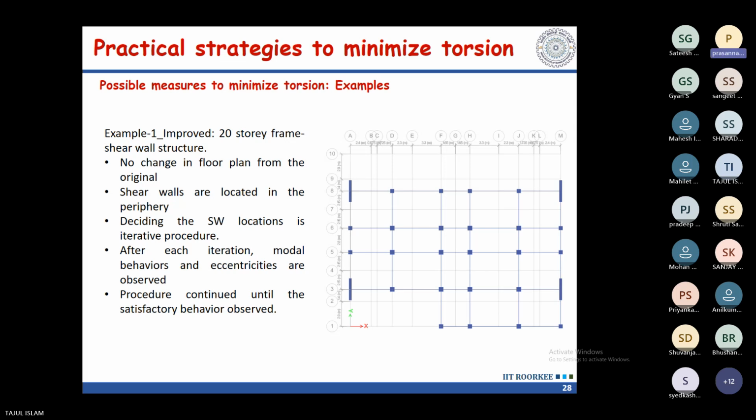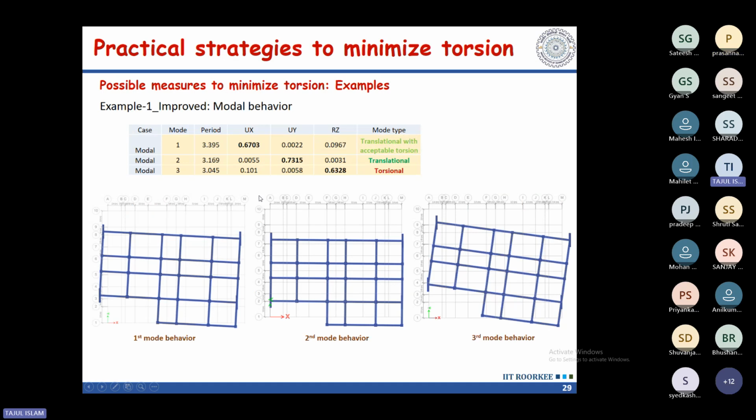But why are you giving a 60% basis for the torsional mode? Yes, I know that 60% is actually a reliable limit. The code says that the combination of modal participation from the first 3 modes should be 60% at least. Correct. But based on our experience, if it is less than 60% in the first mode, you get significant torsion, and your torsional satisfaction is not achievable.